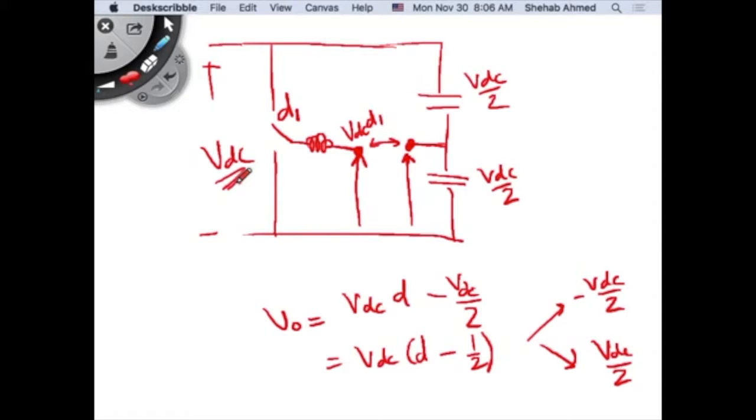And we saw that, if you increase the DC voltage that the switches have to block, how does that affect losses? Remember our switching loss? Remember these triangles that we drew? What was the peak value of the triangle? The turn-on losses, turn-off losses. What was the peak value here for the power loss? Exactly. V is the voltage that the switch is blocking, and I is the current that the switch is conducting, right? So if we're blocking double the voltage, then it's going to affect switching losses, right?